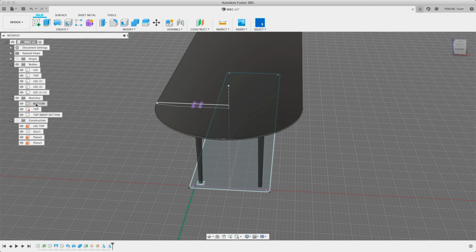I can't make something like this and not render it, so let's quickly do a little bit of rendering here. So A, to open appearances. Appearances are all your materials. Let's go to solid wood, finished wood. Got a few options here. Figured glossy walnut. How about some pine? Glossy pine. Sounds sexy.